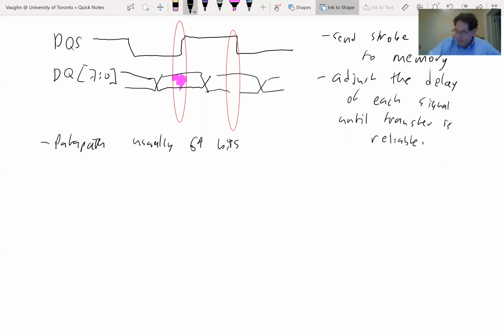An FPGA has to allow more flexibility. And they're fast, 1.6 gigabits per second per pin. So that's what you're getting at the pins. And even higher when you move on to DDR4. Okay, so that's our data path. Data path is fast, relatively wide.